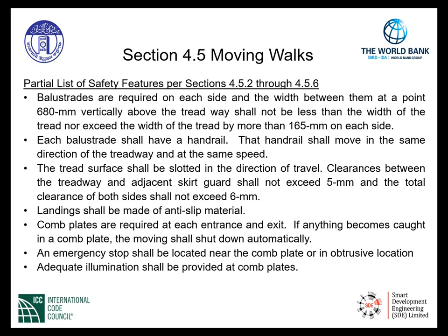Landings shall be made of anti-slip material. Comb plates are required at each entrance and exit. If anything becomes caught in the comb plate, the moving walk shall shut down automatically. An emergency stop shall be located near the comb plate or in some unobstructed location. Finally, adequate illumination shall be provided at the comb plates.